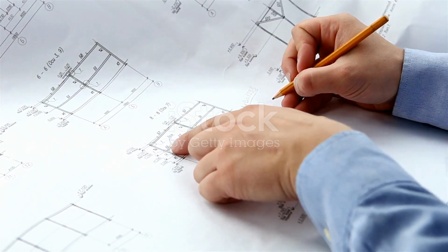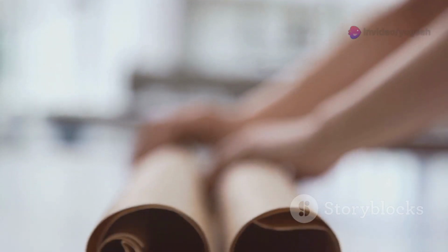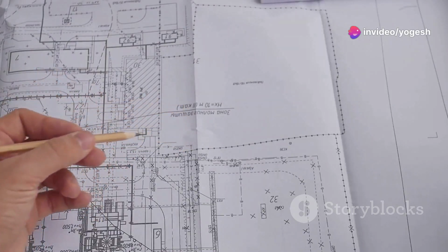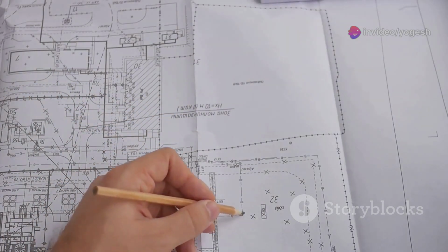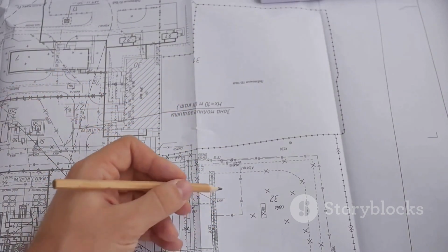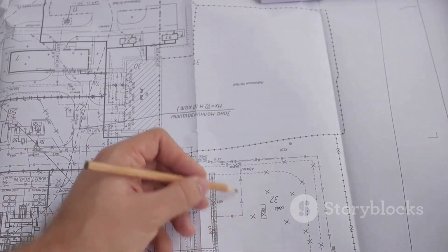Title block errors can derail everything. The title block is your drawing's identity. Never leave it blank or outdated. Unique drawing numbers prevent mix-ups. Revision levels track changes. Always update the revision and fill in who designed, checked, and approved the drawing.